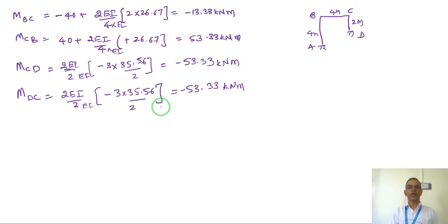So now we can look at some of the frames and see how to identify the degrees of freedom. If the degrees of freedom are identified, things are very easy. You should understand 3 important concepts. If in a given joint a unit rotation is applied, the moment produced at the same point is 4 EI by L, of course with theta equal to 1.